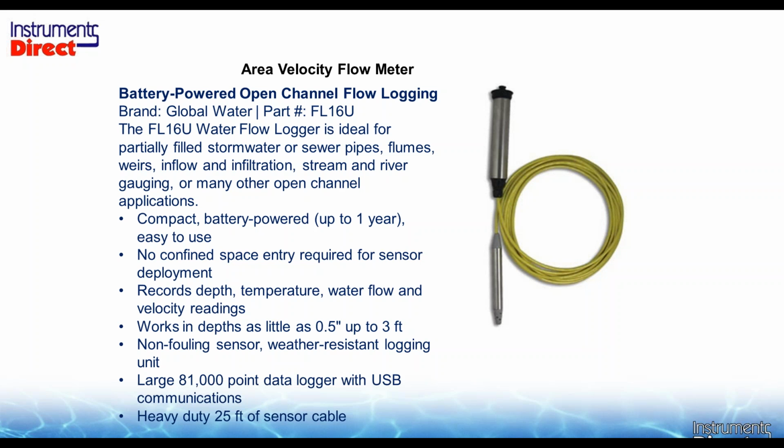Now we'll measure level by monitoring the pressure. In using this methodology, this sensor here is a pressure sensor. You drop this down a line and it gets carried downstream. On most applications, you don't even have to go in the manhole. This is a logger and a module here. This particular portable device, you tie this off in a ladder and drop this down like a fishing line that's going to carry downstream. You would program this device with the pipe size and the slope, and it will use the Manning equation to calculate volumetric flow. So it's making some assumptions here.